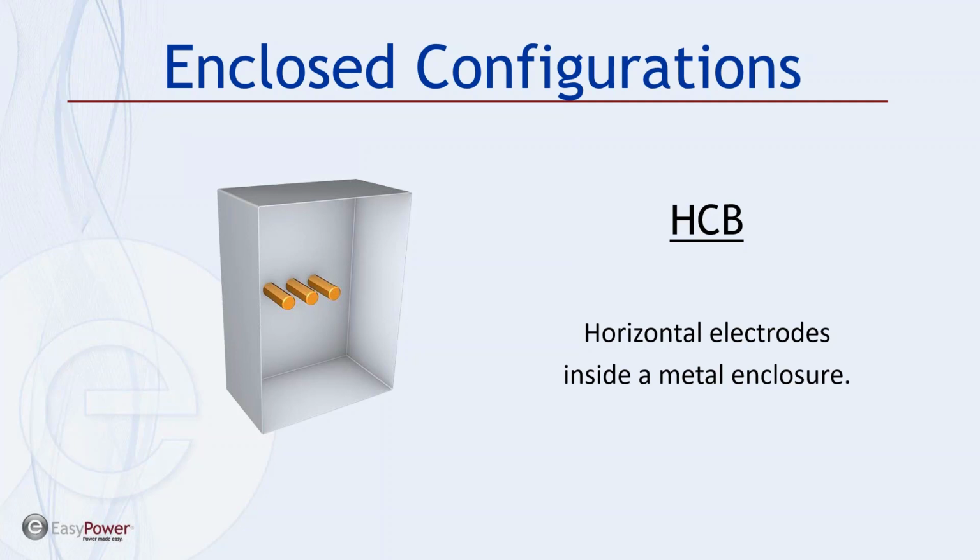For instance, if we were changing fuses for whatever reason in a hot box, and once an arc initiated on these terminals, the direction of radiation would be amplified because of the orientation of the electrodes. So this has been singled out or called out as a separate type of enclosure.